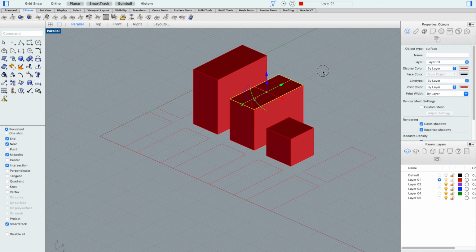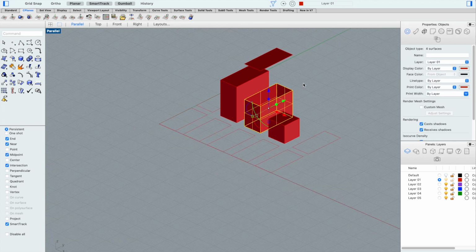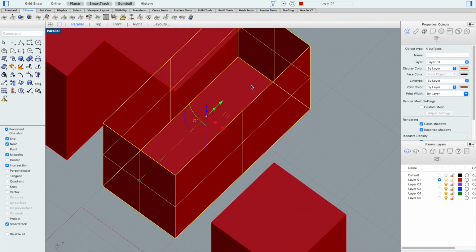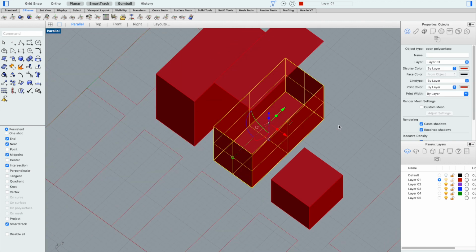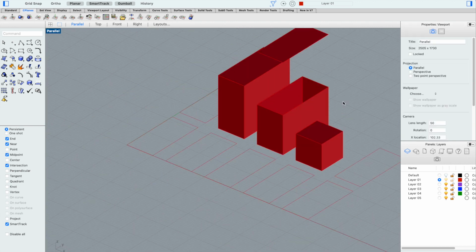Now you can see I've got all of these different surfaces. If I click on this one, I can pull that off, and then I can click on the object again using a shift, look down into the box, click the last one, and join it. My box is now back intact, except for the surface that I wanted to remove. Well, that's pretty easy.